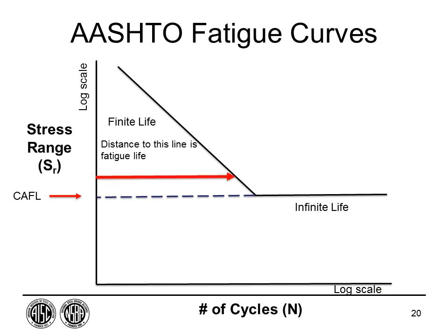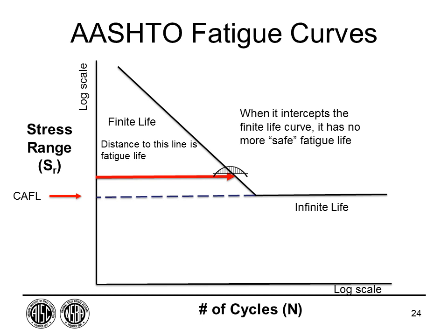So if I want to think about life of a bridge, well, this is the region that I'm worried about. And what happens then simply with time is, if I think my bridge is brand new at some point in time, I have no cycles, but I have a certain stress range value, just simply put, as time marches on, I begin to use fatigue life until I reach the point where I say the bridge has intersected the safe life curve and I don't have any more safe life.